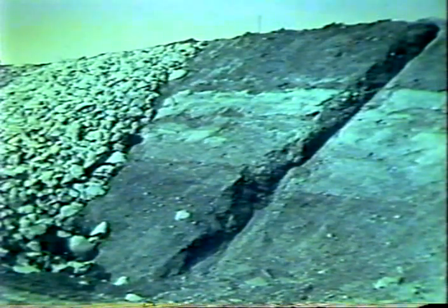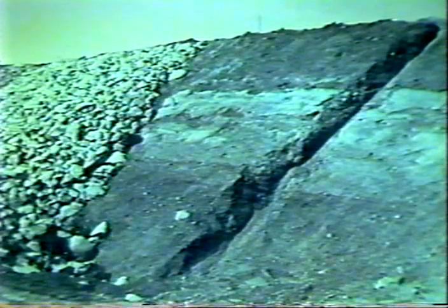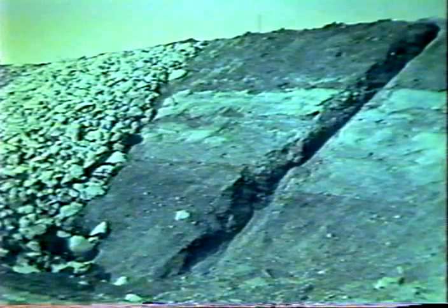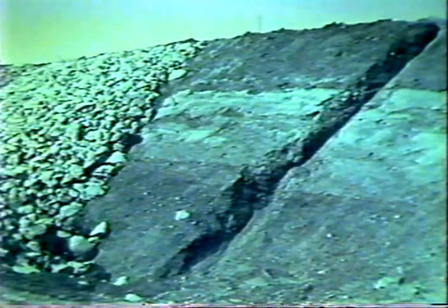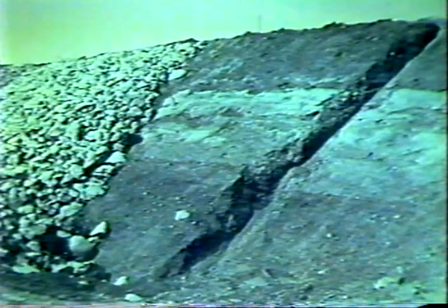Measures incorporated into the bridge structure by design, such as pier shape and depth of foundations, are essential for the prevention of hydraulic problems. However, the emphasis of the research study was on countermeasures at existing bridges. Dumped rock riprap is the countermeasure in most general use. Its effectiveness depends mainly on the adequacy of the rock size and on provision against undermining at the toe and ends. In this example of riprap installation, a rock-filled trench is provided for toe protection.